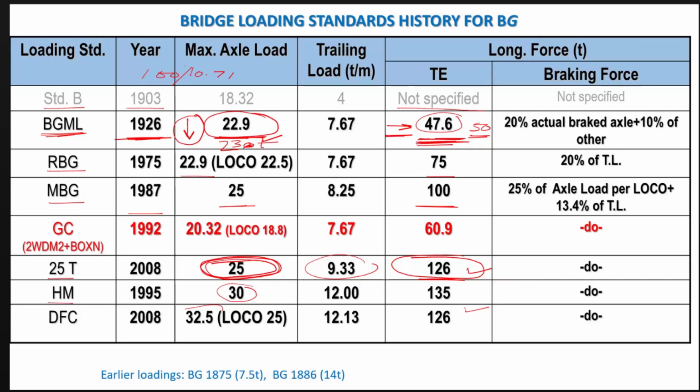Yes. You can raise this issue in the BSc or civil design meetings, for steel girder design and skew. RDSO can help with that, just by checking the drawing. In Western Railway, I checked many drawings and we reduced the clearance by half to 1 meter. So many non-standard bridges we were able to bring to the same drawing as the standard drawings for PSC.